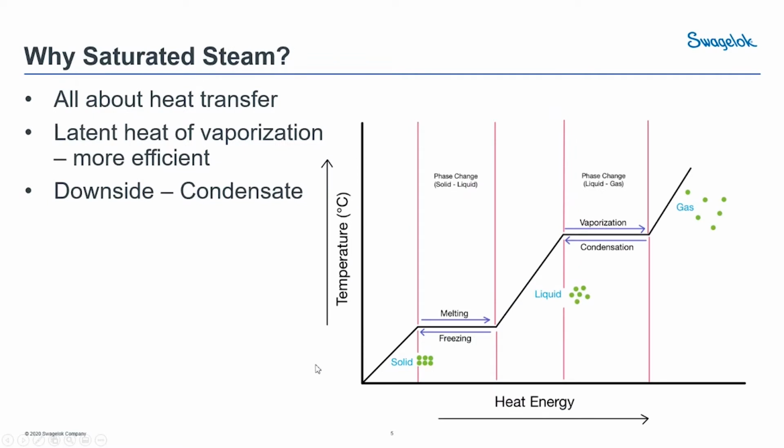So moving on from the system itself, so why saturated steam? Generally for tracing systems, saturated steam is highly advised. And so we want to talk a little bit about why we use saturated steam specifically. What we're trying to do with a steam tracer is to transfer heat.